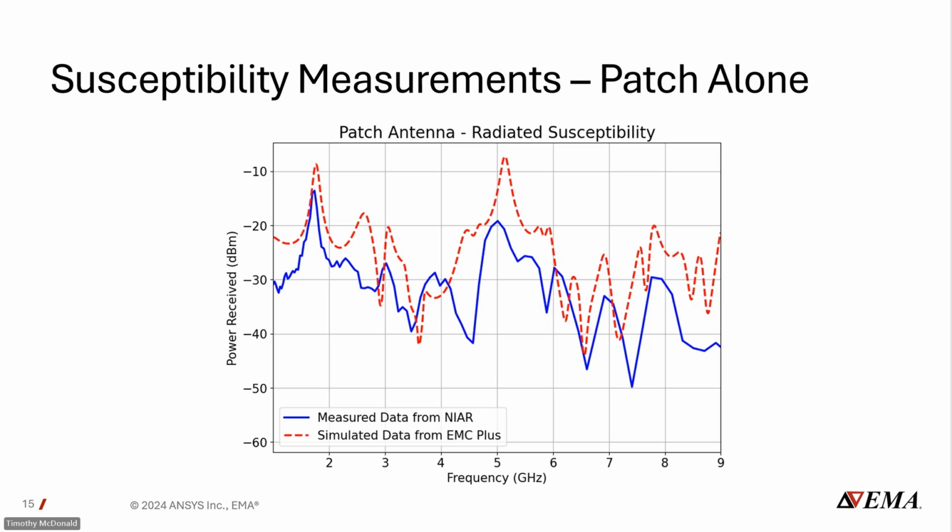We're working in further measurements of this validation campaign to understand some of the uncertainty on both our physical and simulated measurements. But this is a really promising start to show that we are able to accurately understand the frequency range response just from a time domain simulation that runs very quickly. So we can run a fast simulation and get a full comprehensive understanding of the frequency range response of the printed circuit board with its radiated susceptibility.